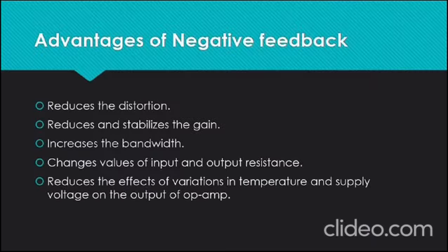The advantages of negative feedback: reduces the distortion, reduces and stabilizes the gain, increases the bandwidth, changes values of input and output resistance, reduces the effects of variations in temperature and supply voltage on the output of op-amp.